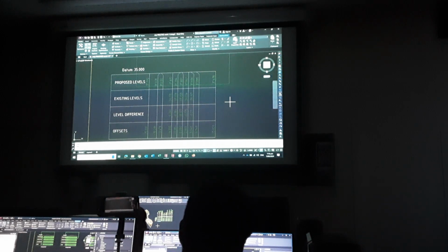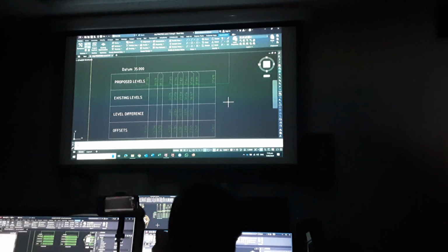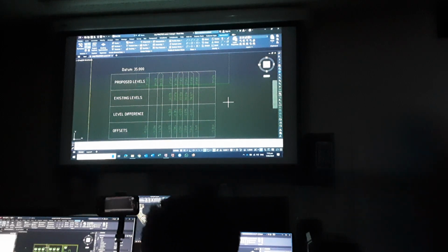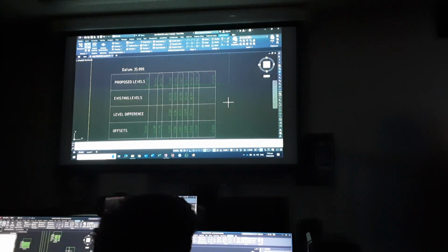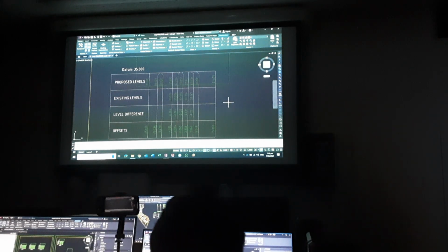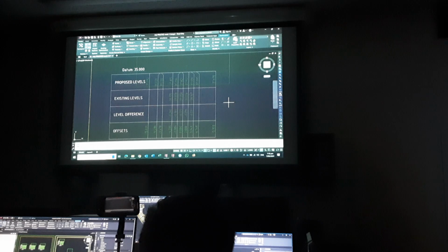With the long section, it'll be distorted, so therefore if any trees are on the long section, you'll have to stretch them to the right line, alright? But the good thing is, all the numbers are calculated for you. Same thing, where it says difference, one column will be cut, one will be filled.